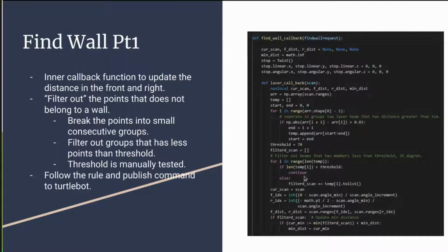Yeah, because if it's too close, 2 or 3 or 5 centimeters away, the angles still won't be great on the scan, so it's not going to distinguish. Or if there are a lot of obstacles clumped together, it's not going to work in that case. We just filter it and get the minimum distance. And here we're actively updating the minimum distance, because when the robot starts, the distance fluctuates a little before it actually settles down.